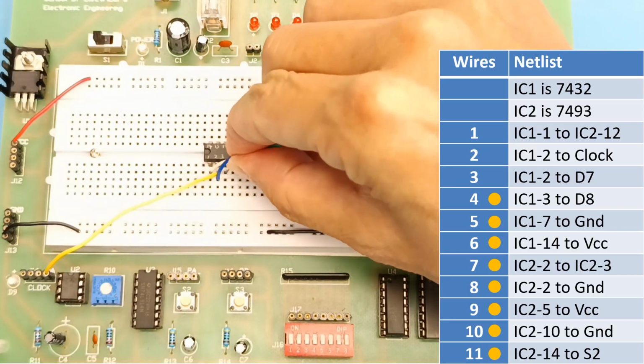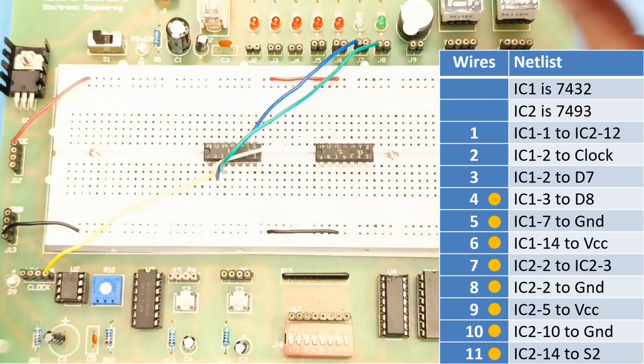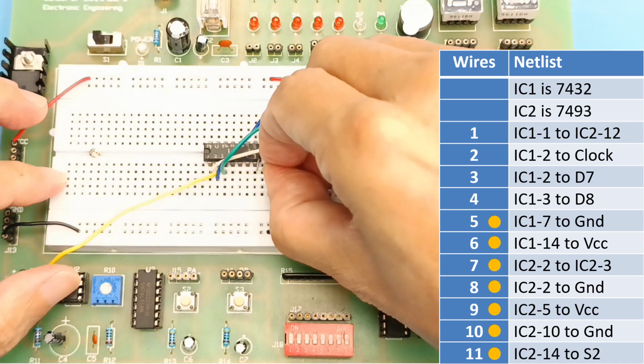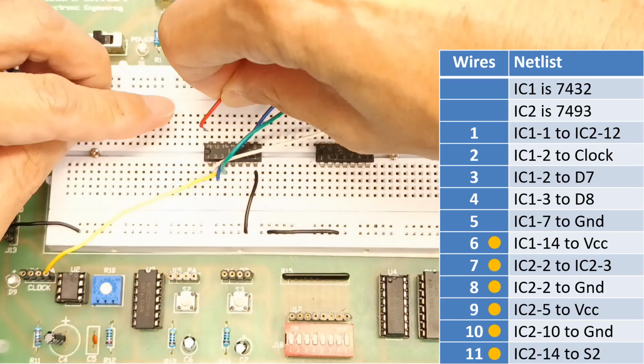IC1 pin 3 to D8. IC1 pin 7 to ground. IC1 pin 14 to VCC.